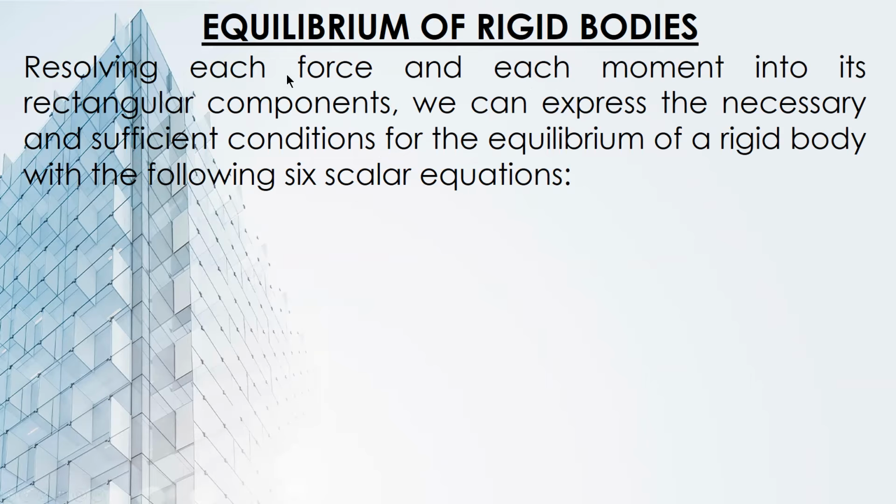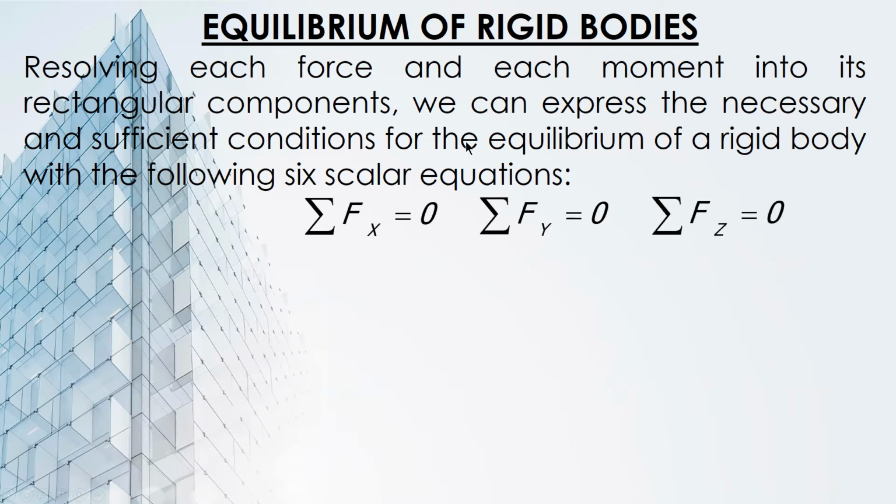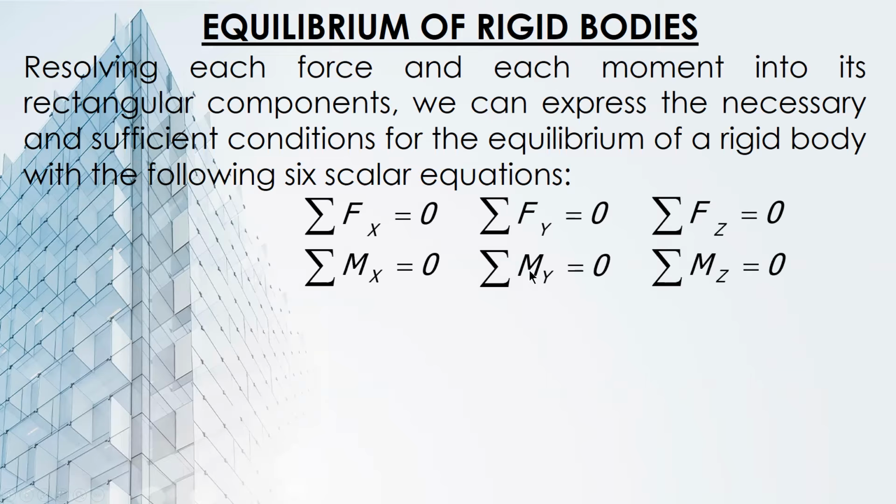If you resolve the force and moment into rectangular components, this is the result. So the summation of force equal to zero, we break into components. Summation of force in x equal to zero, and so with y, and then if 3D, include the summation of force along z. Same with moment. Summation of moment in x equal to 0, y 0, and z 0. For 3D.